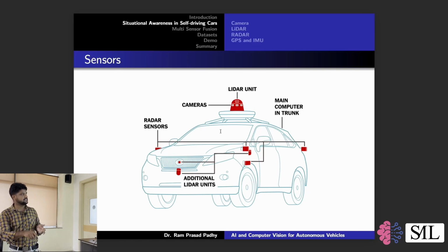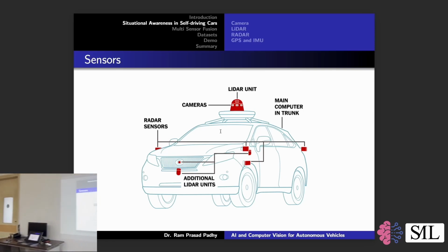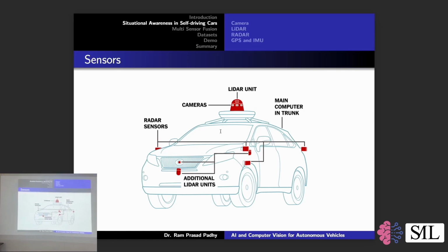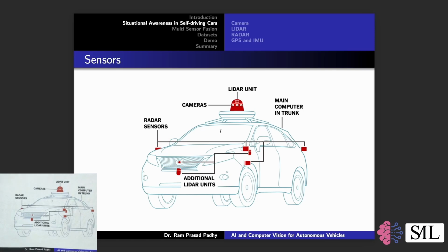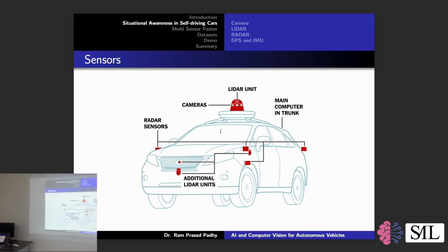Okay. So this is how typical self-driving car sensors are connected, and you will see that the camera is generally connected at a place where we can see the front view. Okay, here in this diagram you can see the camera is connected at the top, because in this diagram multiple cameras are used, and that covers the whole 360 degrees. Okay, if you want to use a single 360 degree camera, it might not work, because in 360 degree cameras you get this fisheye view. Okay, it will not look like the way that we see the environment. So you have to use rectilinear cameras, which give you the way that we generally perceive the environment, right? Rectilinear views that have an overlapping field of view, so that you can cover the 360 degrees.